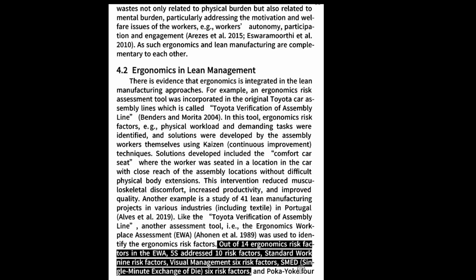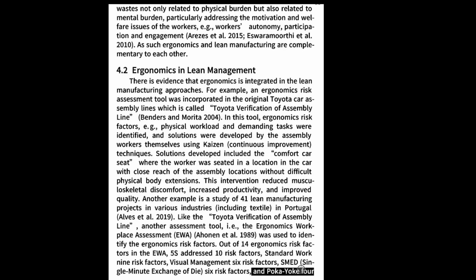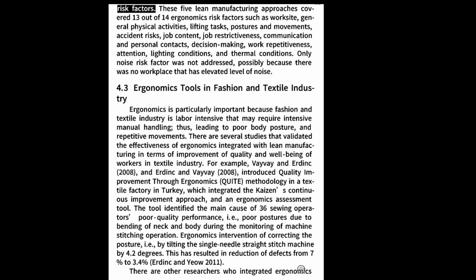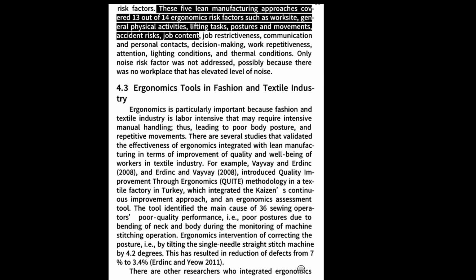Out of 14 ergonomics risk factors, 5S addressed 10 risk factors, standard work 9 risk factors, visual management 6 risk factors, SMED, single minute exchange of die, 6 risk factors, and Poka-Yoke 4 risk factors. These 5 lean manufacturing approaches covered 13 out of 14 ergonomics risk factors such as worksite, general physical activities, lifting